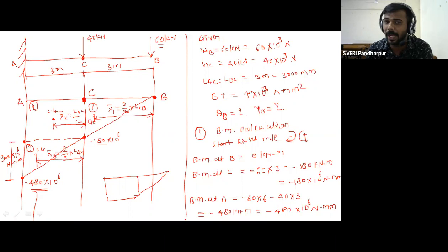So I will consider point B as the reference point for the X bar calculation. For section number 1, X1 bar is equal to 2 by 3 into the length of BC. But while calculating the X bar for section number 2 and section number 3, every X bar formula is applicable for that particular section only. Here, for section 2, which is the rectangle, the CG is concentrated at the center, so its X bar is L of AC divided by 2, which is measured only up to point C.